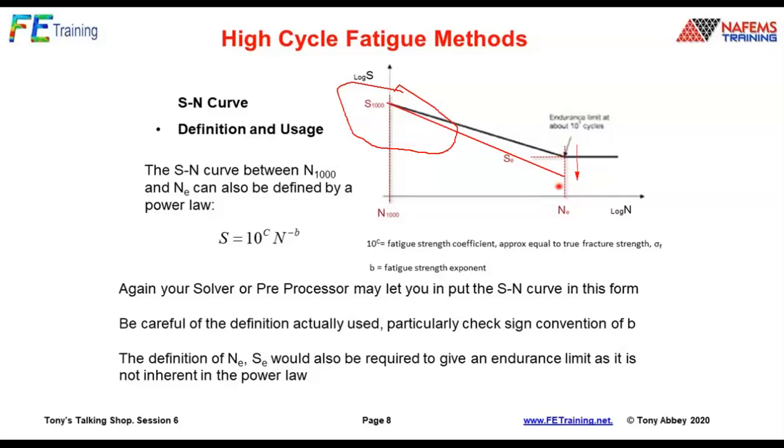Just again, a little bit of an aside, I can do my stress calculations, I can come up with a linear FE analysis, do a mesh convergence study, get a stress at a particular point. That well could be dominated by the actual service terms I use, my correction factors due to corrosion, different forms of machining, different metallic structures, whatever it might be. That might be more important than actually getting an accurate calculation. We want to get an accurate FEA calculation, but if we don't put real life factors on there based on experimental evidence, then we're kind of fooling ourselves.